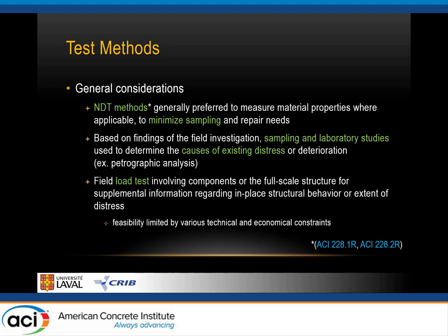For sure, depending on the actual condition, oftentimes we'll need to sample and perform some extra tests in the lab, and the sampling must be designed in order to answer the actual needs and to be representative of what we have on the structure. And like Ashok was saying, in very specific cases, we'll have to perform some load testing on site, but these for sure require some detailed analysis, because in some cases feasibility may be quite limited depending on the technical and economical constraints.